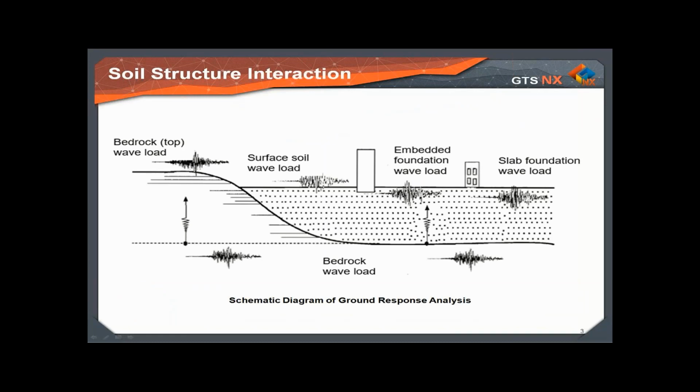Soil structure interaction is the phenomenon in which the response of soil and the movement of the structure influence each other. When external forces such as an earthquake act on these systems, neither structural displacement nor ground displacement is independent of the other. Unlike an above-ground structure, the response of an underground structure subject to an earthquake is mainly controlled by the ground displacement.